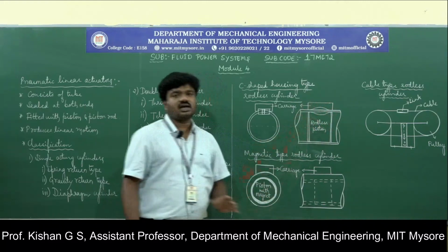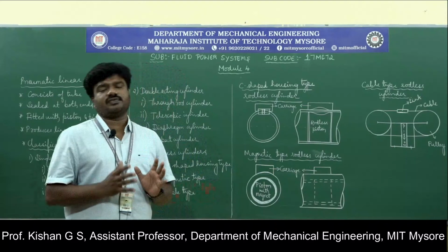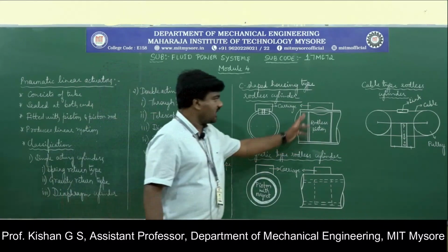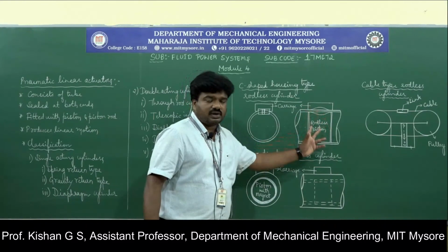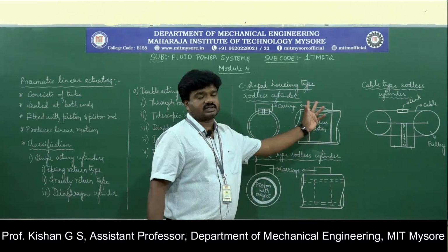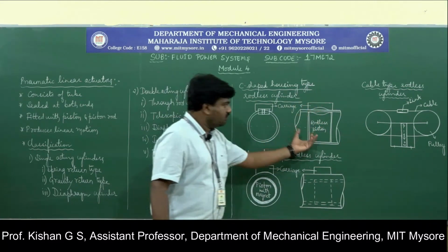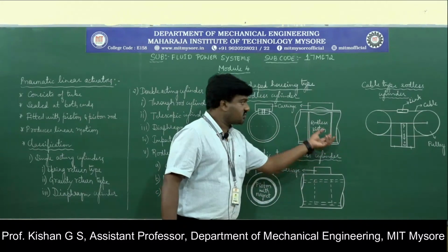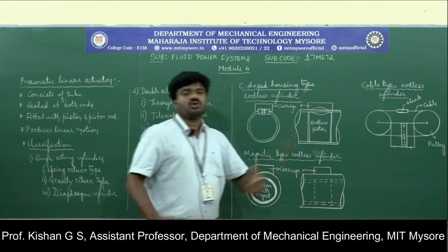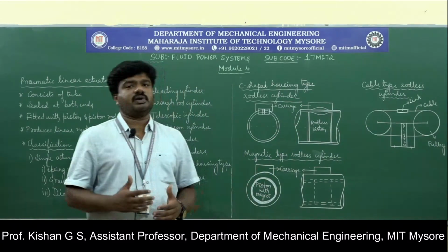The piston is housed inside the body of the tube or cylinder, wherein onto the sides or the end of the piston there will be a connection at the projected part, which is nothing but the carriage assembly onto the cylinder tube. So the movement of the piston leads to the movement of the carriage along the same direction, such that whichever way the external load is attached, that motion will be derived.